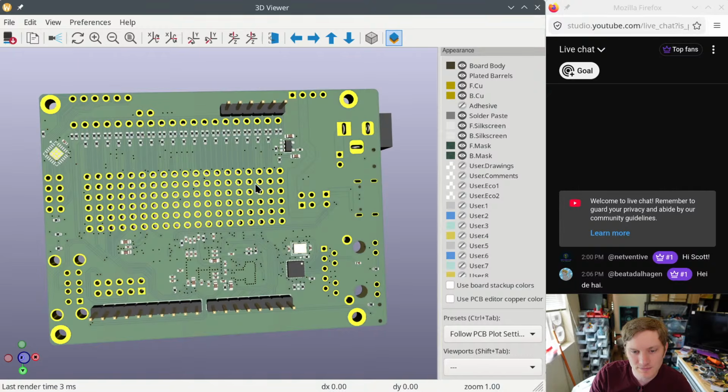This is the circuitry for the Ethernet chip here, and it needs its own crystal. I put it on the back because I could route these pins straight to the connector. If it was on the top, it would have had to be swapped.